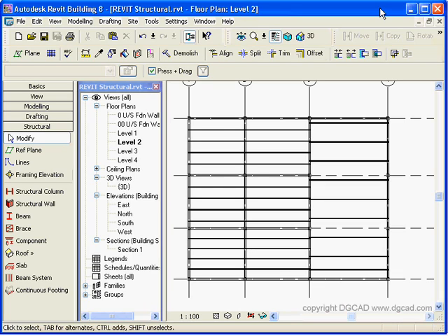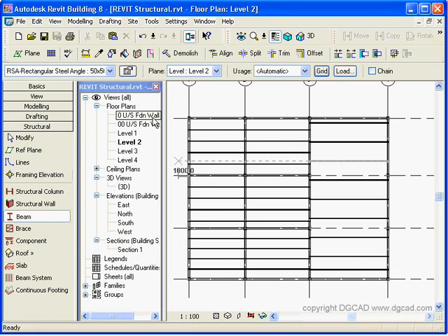And that concludes our part 2 of our REVIT, the structural tools in REVIT Building 8. Just a couple last notes. Remember when you go in and you're drawing beams to have a look up here and check your elevations and usage and whether you want to use a grid system or not, whether you want to load it or chain. So you can put in beams in various ways, but you should be checking that the plane you're working on in here, and using grid option you can then pick the grids and it will jump over columns.